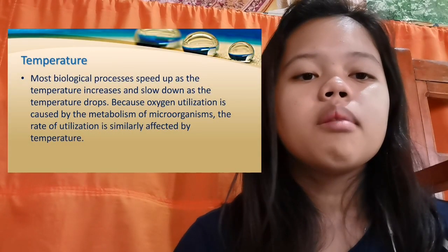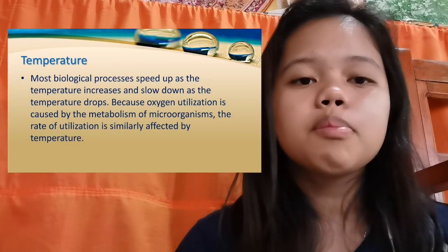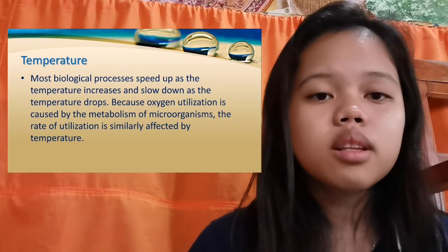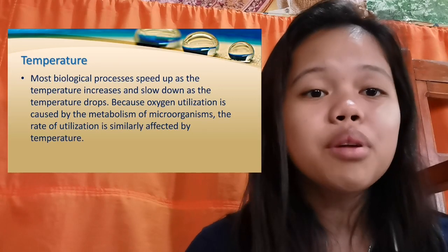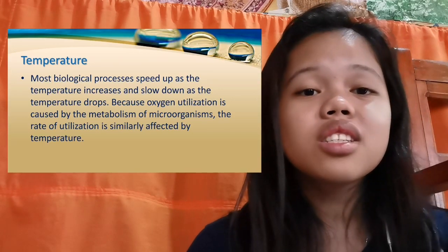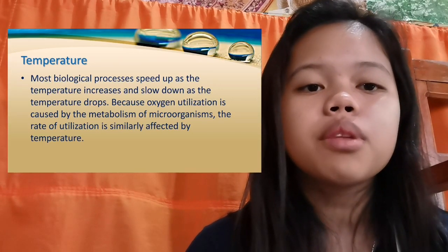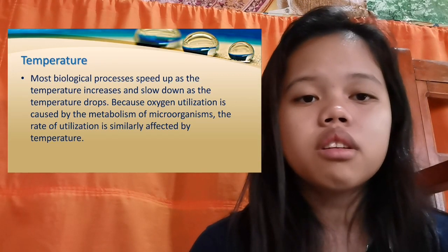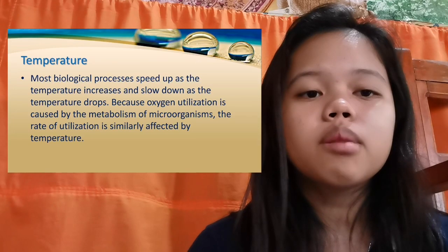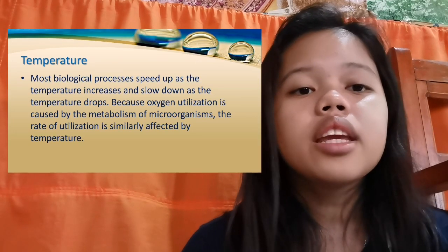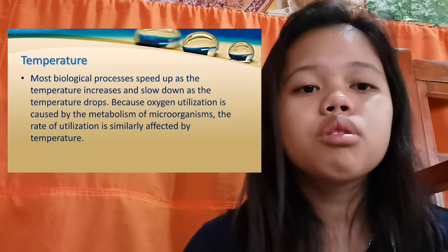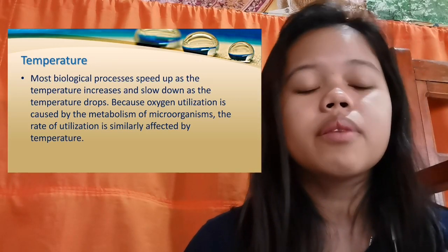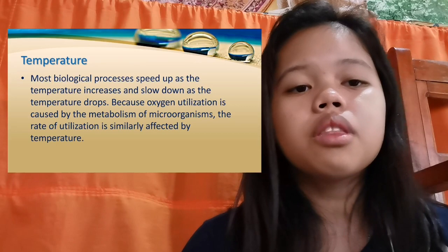Temperature. Most biological processes speed up as the temperature increases and slow down as the temperature drops, because oxygen utilization is caused by the metabolism of microorganisms. The rate of utilization is similarly affected by temperature. Ideally, the BOD rate constant should be experimentally determined for the temperature of the receiving water. There are two difficulties with this ideal.